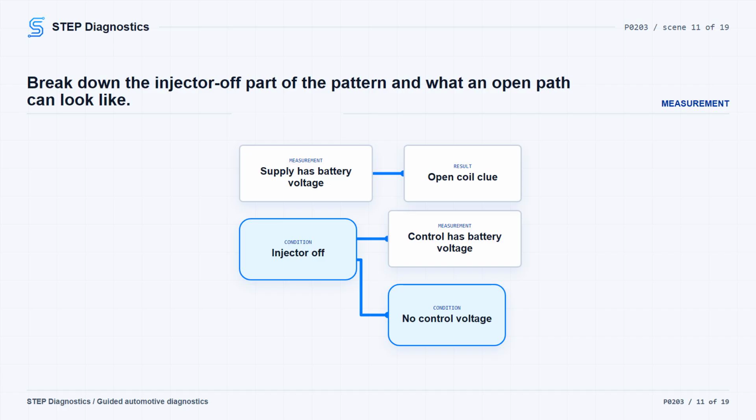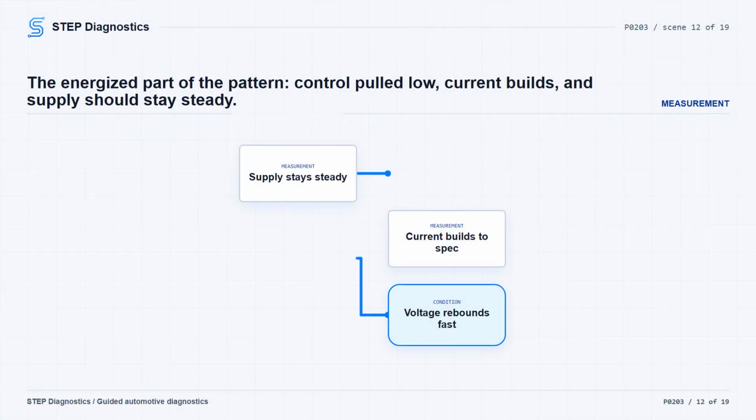If the control voltage does not pull near 0, think resistance in the control circuit path. If the voltage drops low and then quickly ramps back toward battery voltage, too much current flow with driver protection shutdown or a low side driver failure could be indicated.